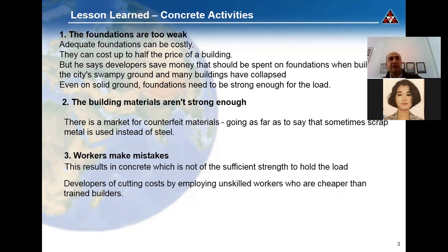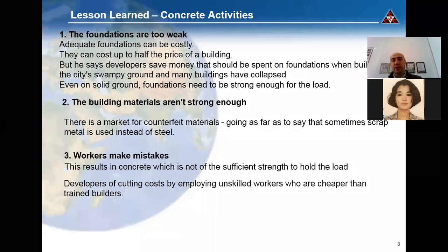So you need to take some samples from the new concrete and create some cubes, and after a few days, like 7 days, 14, 21 and 28 days, when these cubes of concrete have lain in the high humidity box, be it water or sawdust with water, you need to check them in the laboratory on compressive forces.